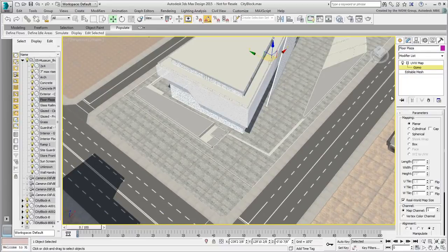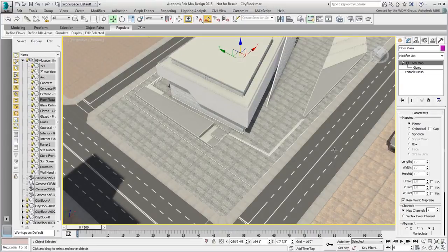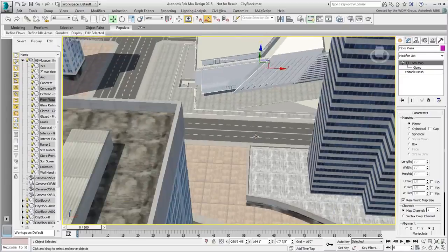You can certainly try to do that in Revit and update the link. However, as you get comfortable with 3ds Max's material editor, you may find it easier to do that kind of work here. This is the approach you will take for the rest of this project. In fact, once you know the geometry is finalized, you can opt to bind the FBX file to make it a permanent part of the 3ds Max scene.